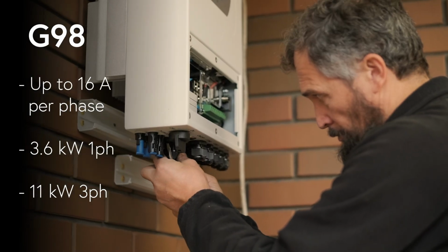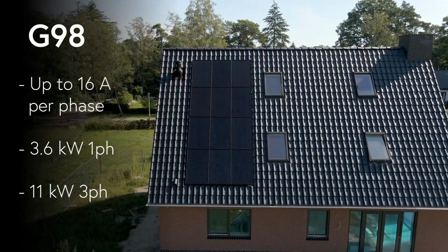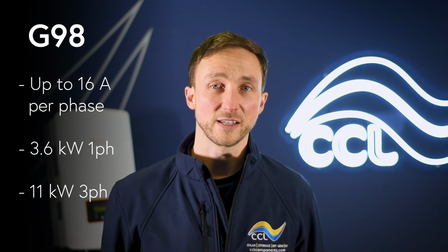Before we jump into the register, let's quickly break down what G98, G99 and G100 mean. G98 and G99 are UK engineering standards that ensure all generation equipment, including solar inverters, operate safely on the grid without causing instability. G98 applies to smaller installations, up to 16 amps per phase, which translates to approximately 3.6 kilowatts for single phase and 11 kilowatts for three-phase setups. These devices work on a fit and forget basis, meaning the DNO only need to be notified after installation.